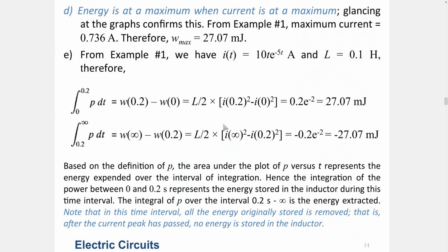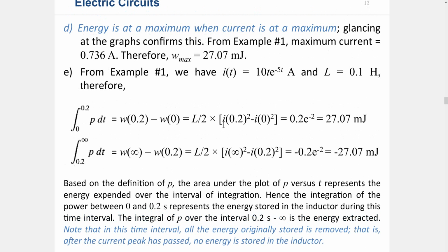This is how inductors operate with respect to time. They need currents that change with respect to time. So we introduce the alternating currents, and we will mostly be working on alternating current circuits when we are dealing with inductors and capacitors, because under direct current conditions, the inductor is a short circuit and the capacitor will be an open circuit, as we will explore.